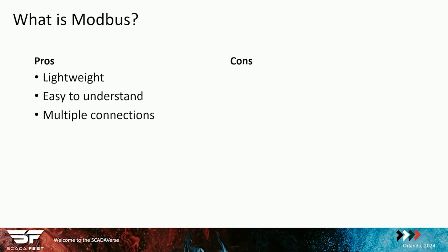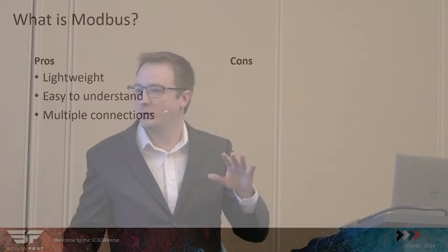And the other thing Modbus does, it's not session-based. You can have multiple concurrent connections to the same PLC pulling data. This lets you get way more data back to your master system compared to other protocols where you have to wait and do serialized comms one at a time. You can do these in parallel. So if you have 10 different sets of registers you need to read that get distributed into what we call read locks in VTScada, you can pull all 10 simultaneously if you have 10 connections to that PLC that you can use. Where other protocols, you have to wait for the first one to go, then the second one, then the third one. So Modbus can be very, very fast to get data back as well.